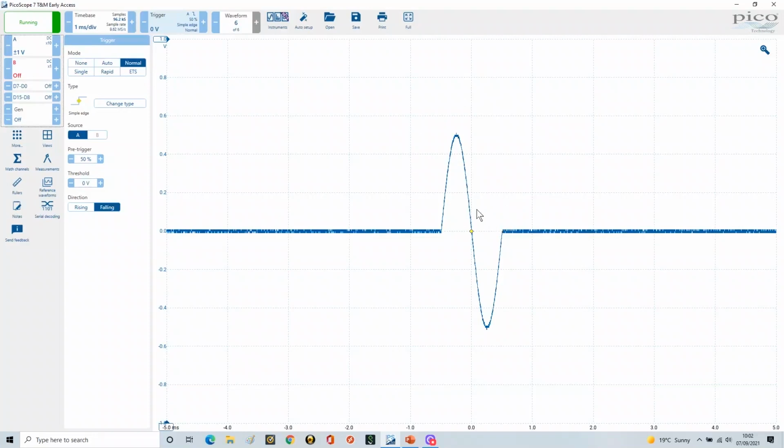Now the thing is that there are times when you might be looking at the signal and you want to examine this signal in detail, but then all of a sudden another signal comes along, and the one you were looking at all of a sudden now changes. And this is not very good. Especially this happens particularly when you're looking at or analyzing protocols, and you want to look at, for example, SPI, which we're going to look at in this video, to show that we can capture events and analyze events before another communications event occurs, because we might be analyzing that signal and thinking, oh, hang on a minute, it's just disappeared and changed because some more data has come out, but it's different from the one I was looking at. And this is where single shot comes in.